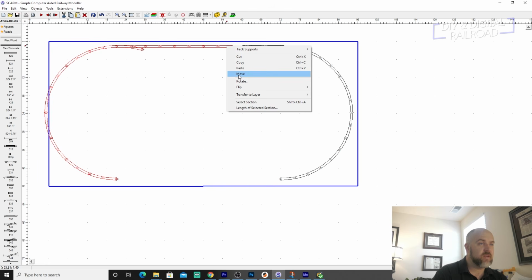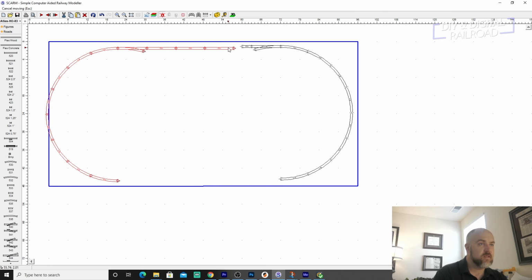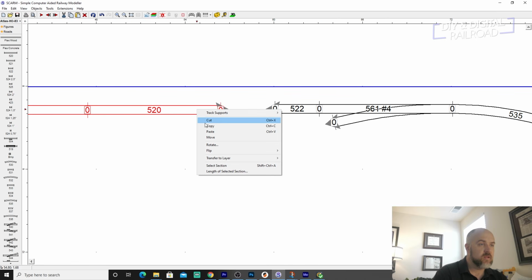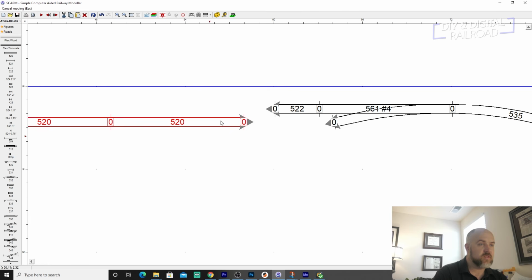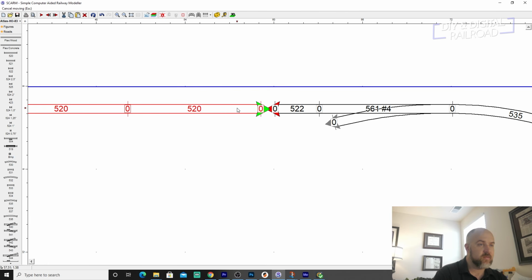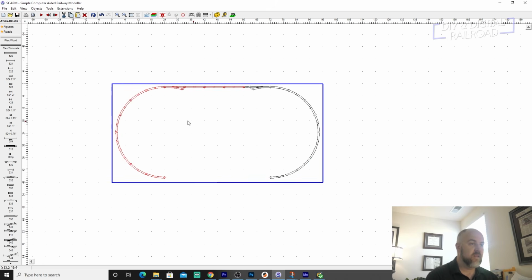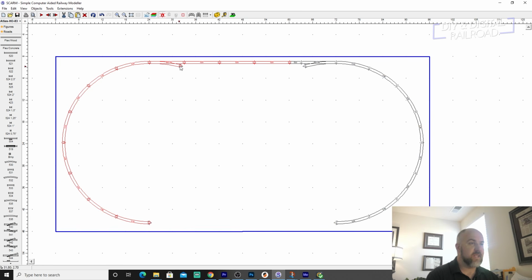Highlight this whole unconnected section, and when I move it, you can see, I'm actually going to zoom in on this. When I move this whole section, you can see once it lines up, they go red and green, and once they're like that, they'll connect. All you have to do is click. So we have this section, and we need to finish this off.